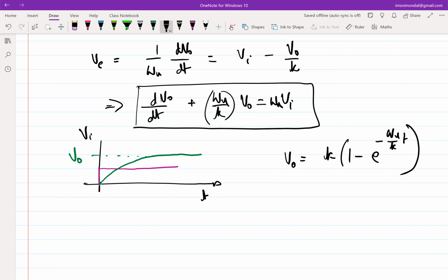Any questions? So in any type of first order settling, what is the most important thing that you are looking at? Time constant. And what is the time constant in this case? Yeah, k by omega u, right? Or 1 over omega u by k. You will see this omega u over k keep repeating across a negative feedback loop in different formats. So keep an eye on this omega u by k, where it goes.